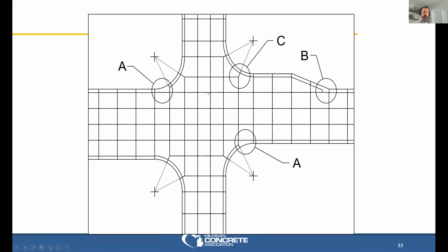To allow for that slip form paving, we adjust our curb and gutter profile, and that gutter pan extends out to absorb that little triangular sliver that would have occurred in these two locations marked as detail A. We also combine our transverse and/or longitudinal joints at this intersection box area where we get close, and then go through the arc, or go snap perpendicular to that arc.